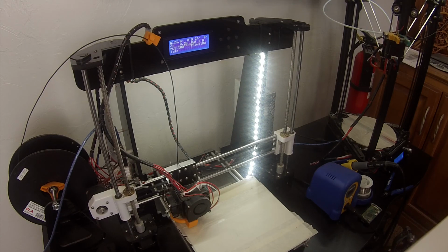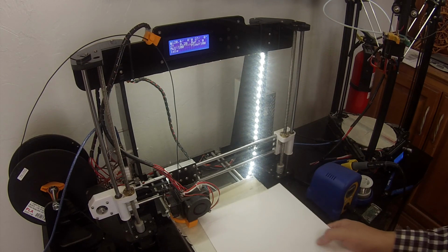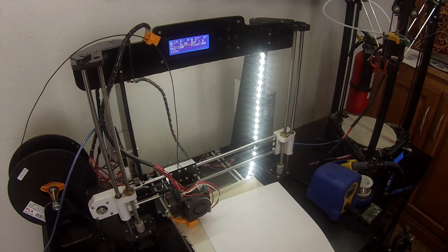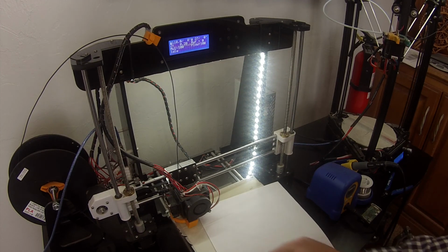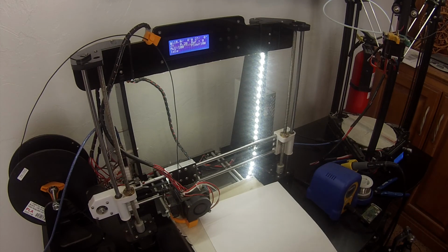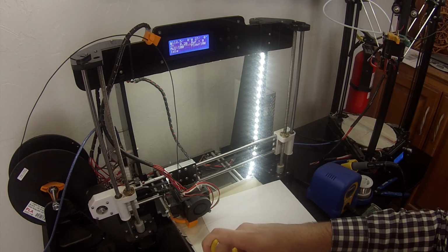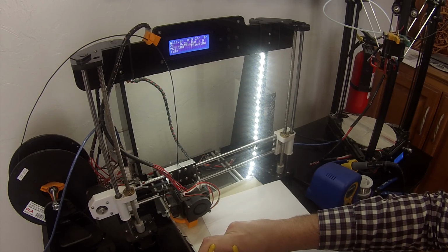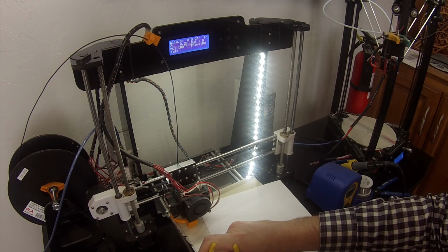Adjust the screws so that the print bed will just barely touch the paper at a Z height of 0. So in this case, I would simply take a screwdriver, puncture through the top of this plastic to hold that screw in place as I either tighten or loosen the thumb screw underneath.